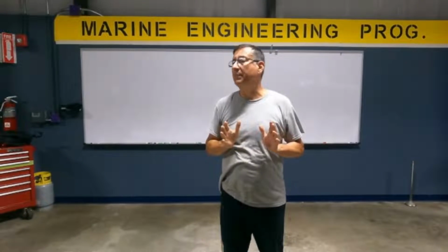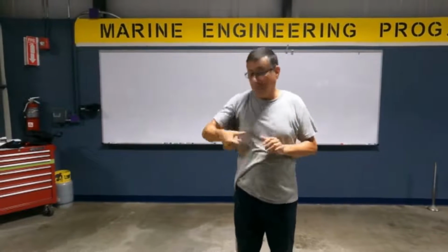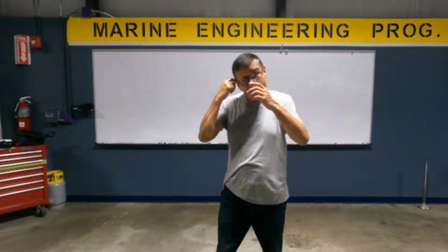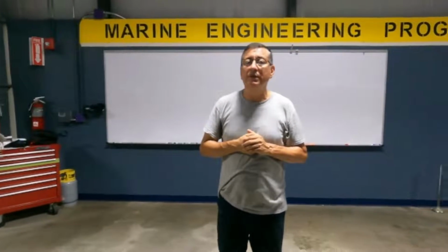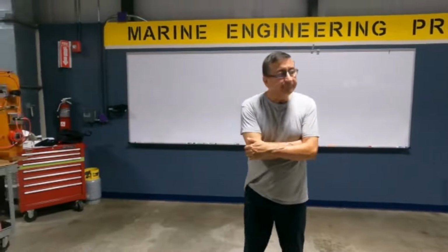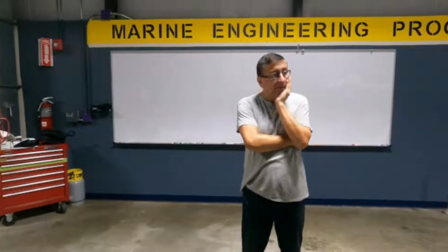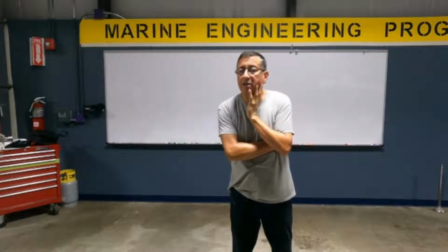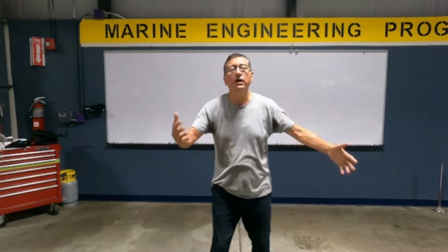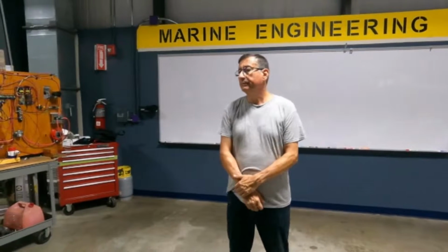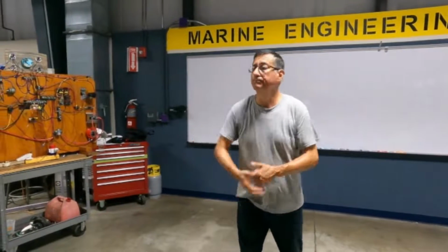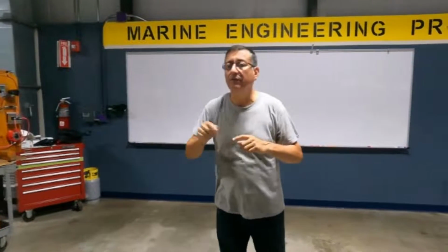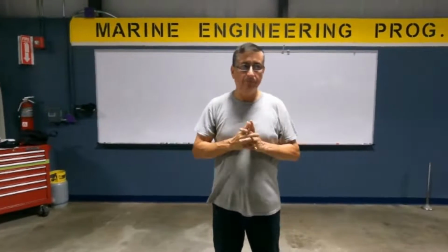If I don't return, what happens? Nothing. You try to start, you try to turn on. This is the most common problem in circuits. Hey, my friend, what is your problem? No, I don't know, Mr. Lopez, but it's okay. Check the circuit. Where is the ground connected? Oh, sorry, no ground. Or the ground is loose. Or the ground is corroded. The ground is the negative. It's the return in DC. That's okay?